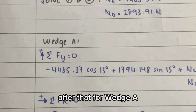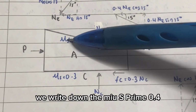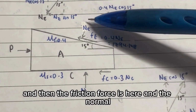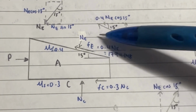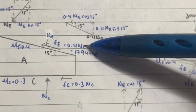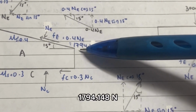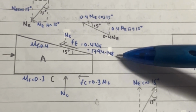After that, for wedge A, we write down the mu s prime 0.4, and then the friction force is here, and the normal force of E. We assume E here, and then we have the answer for Ne. Then we replace here, and we got 10794.148 Newton.